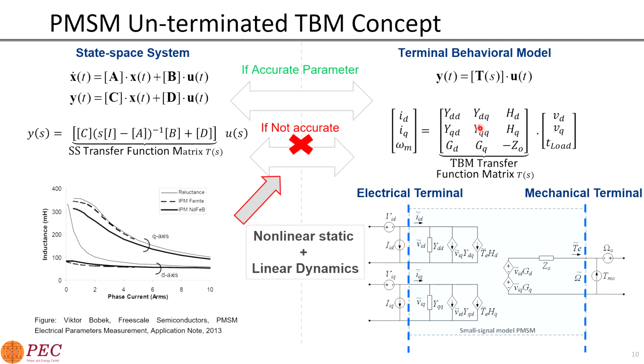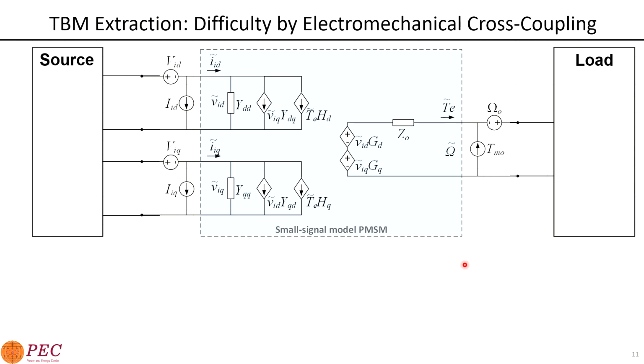And the machine contains not only an electrical part, but also mechanical and magnetic parts. If we follow the same governing equations, we transform the torque into voltage and the speed into current, and we could get a totally equivalent circuit describing the system, like the bottom figure shows. And on this page I will show you why there are always some couplings from upstream and downstream.